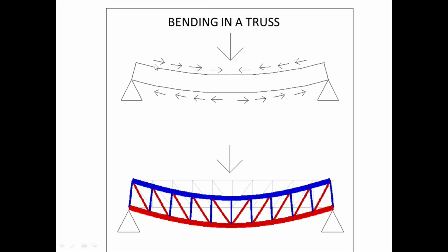There it is again illustrated. The top part of the beam is going into compression. It's actually shortening. You can see in this exaggerated drawing that edge is shortening. That edge is slightly lengthening. It's being pulled in tension. Compression, tension. This is a truss.